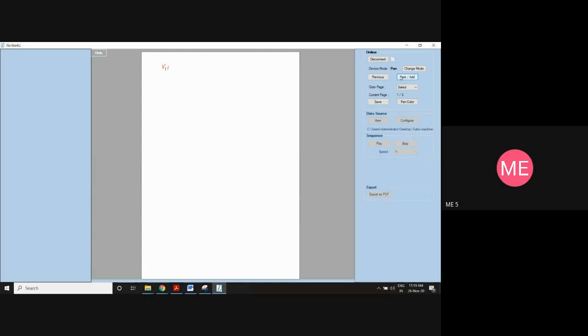Yeah, both are asked. He's asking V1 as well as alpha 1. Okay, V1 is equal to, I'll use Pythagoras then. So you tell me what is V1 in meters per second. Similarly, tan alpha 1 is equal to VF1 by VU1. Find out alpha 1, tan inverse of VF1 by VU1. VF1 is given in the question, no? 10. V1 we just now determined, that is 32.151. Tell me the value of alpha 1 in degrees.